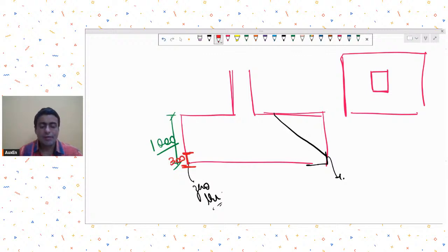So see, if you have given this minimum 300, so already because of this that you are going to maintain, your thickness at every section will automatically go up. Otherwise, what would have happened? The thicknesses at corresponding sections would be lesser, but because we are maintaining minimum 300 at the free end, automatically your thickness at every section increases. That's a plus point.